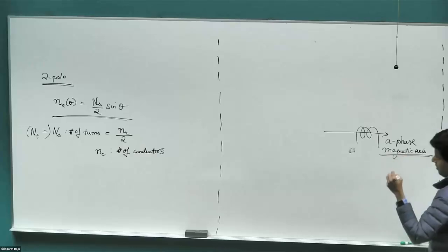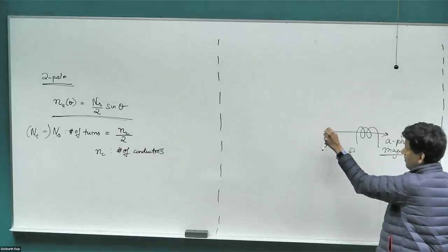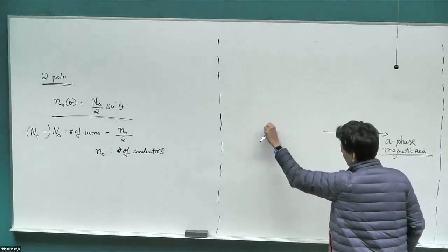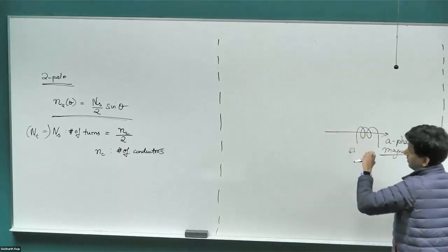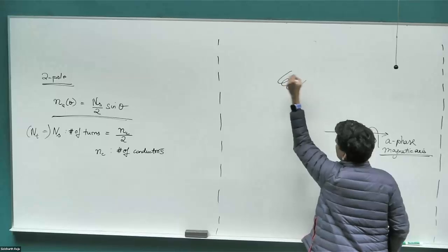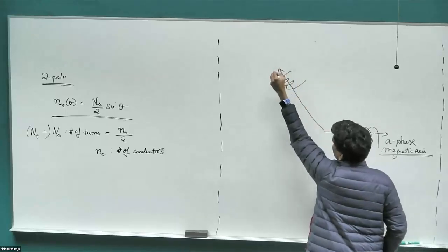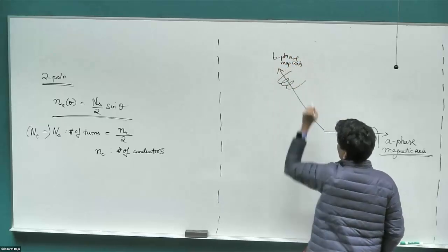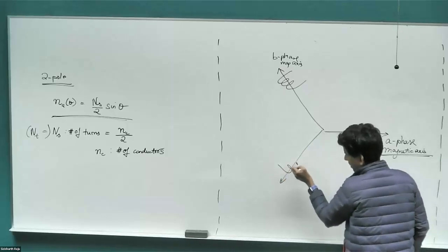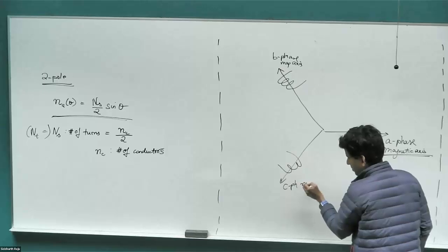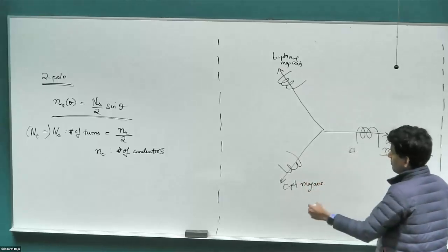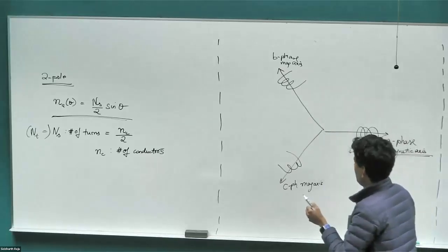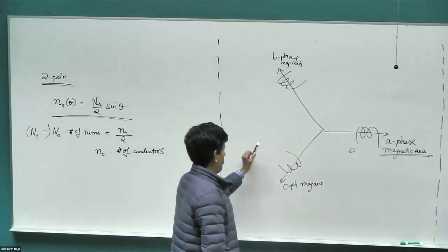Going back to Professor Riaz's animation, the H field due to the A phase winding was increasing to a high positive value, then going back to zero, negative, coming back to zero, increasing. So it was always along this x-axis. The B phase H field would have been along this axis, so this is the B phase magnetic axis. Similarly, we had our C phase magnetic axis. The combined effect would have been a magnetic field rotating in space, completing a full rotation every cycle of the input frequency for a two-pole motor.